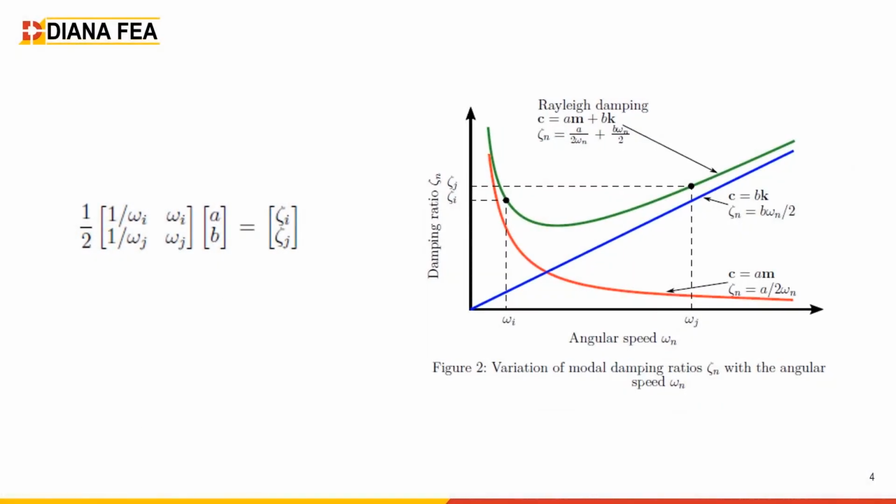Okay, here we go. So as you remember, we were at this stage where basically we need to identify the frequency that we are going to use, the Rayleigh frequency, and then to specify some damping ratio. And then from that, we will be able to derive A and B.